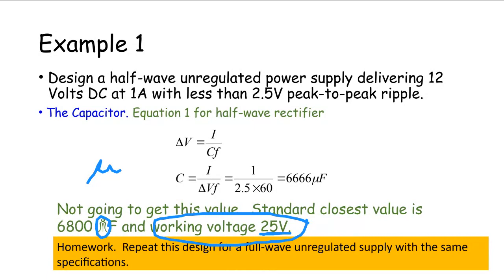When you connect the capacitor the right way, the positive to the positive terminal and the negative to the negative terminal, the polarization creates the dielectric and you get the capacitor behavior. If you reverse it, the dielectric becomes conductive and you short circuit the capacitor. I was making a joke in the last class about blowing up capacitors, and that's what happens. So within a particular family, all of the capacitors will be made more or less the same.